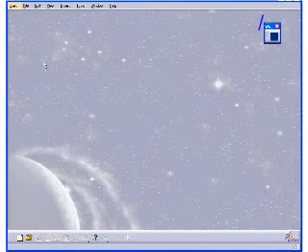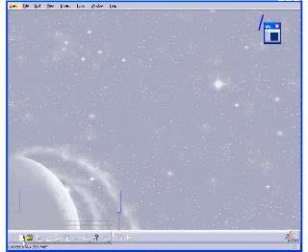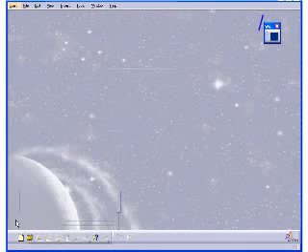Welcome to our introduction to the Sketcher workbench. Let's start by creating a new document. We're going to select the New Document command from the standard toolbar. If you don't have this toolbar, select View, Toolbars, and select Standard.